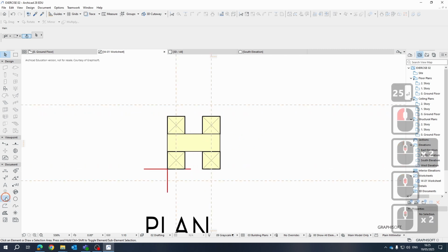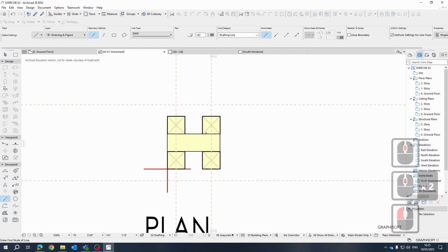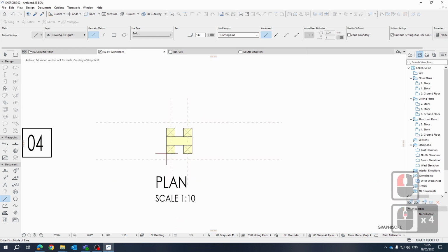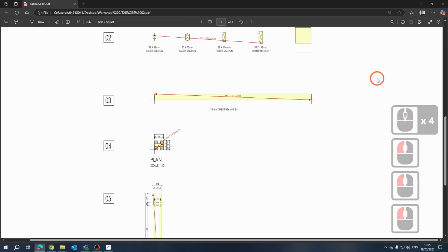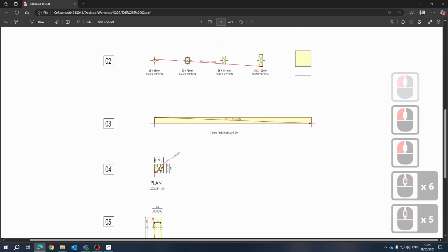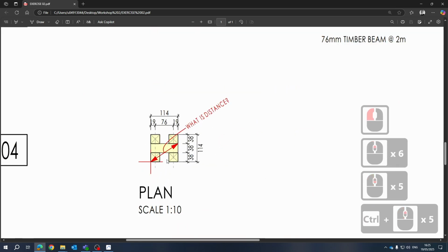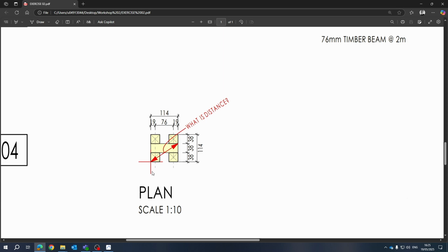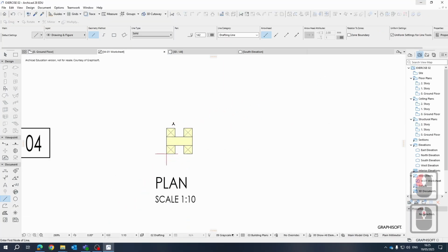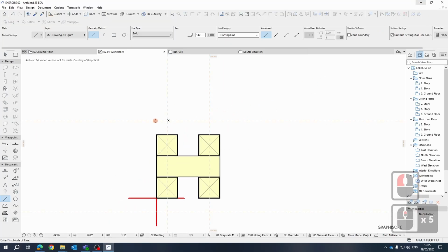It just means if I start drafting some line work, I can now put in the information that is required for exercise 4. Okay, so for exercise 4, I'm just going to put in some guidelines. So center lines, instead of drawing the nuts and bolts, sometimes we can use center lines that will denote a fixing line or a center line of where fixing will need to be considered around. Okay, so for now, I just want you to draw center lines. We're not going to draw nuts and bolts. We will get to that later.